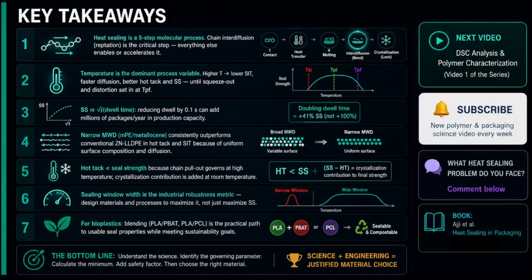Narrow molecular weight distribution always beats broad molecular weight distribution. Uniform surface composition, no low molecular weight surface segregation, predictable diffusion across the interface. 5. Hot tack is always lower than seal strength, because crystallization contributes to ambient temperature strength, but not to hot tack. The difference between the two tells you how much the crystallization step is controlling the final bond strength.